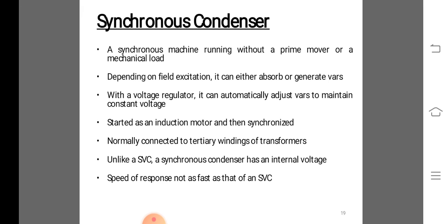In the thyristor controlled reactor, the inductive reactance is controlled by the thyristor for a limited range of operation, and the relationship between the inductive current and applied voltage is represented. As the inductance is varied, the susceptance varies over a range within the limits B_L minimum and B_L maximum, corresponding to X_L maximum and X_L minimum, while the voltage changes by delta V volts.